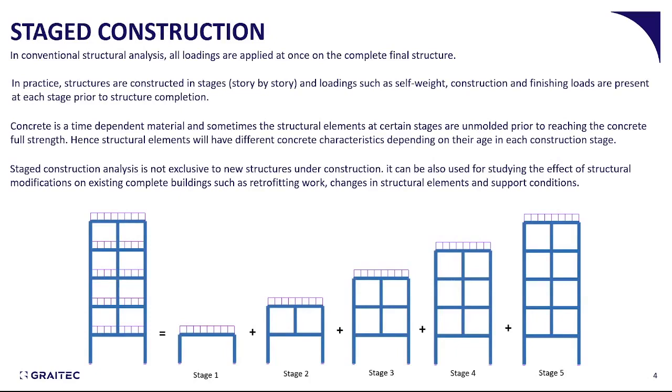In conventional structural analysis, all loadings are applied at once on the complete final structure. However, in practice, structures are constructed in stages, story by story. And loadings such as self-weight, construction loads, and any finishing loads are present at each stage prior to structure completion.